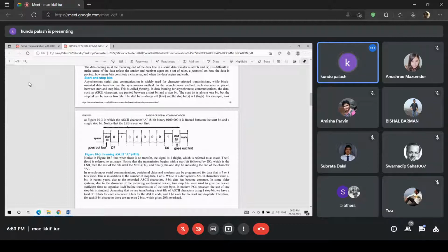If the receiver does not send the start bit, then it will reject the bit. Again, the sender has to reinitiate the process by sending the low bit as a start bit of fixed duration. Then 8 pulses, either low or high according to the byte information, will be sent, and at the last a high stop bit will be transferred.